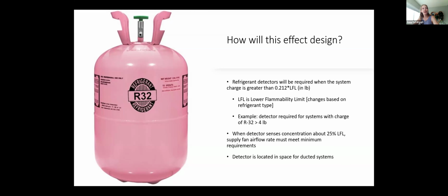If we can provide that natural ventilation solution where we have the 4-inch pipe to the outdoors, that's going to be a very cost-effective solution rather than providing the mechanical ventilation. You're still providing the detection system as well as the refrigerant safety protection around the shaft.